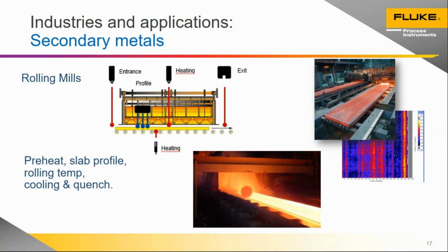It essentially appeared in a thermal image to look just like this, where you see a bright red hot material coming out, whereas the normal view of the operator looking from the control room, he wasn't able to see it until much later. So it provided an extra edge in safety and ability to control that by using the thermal image.